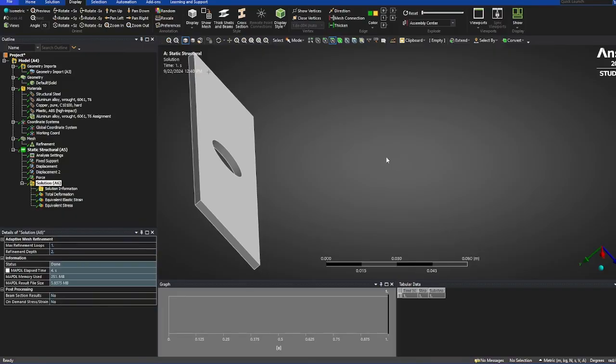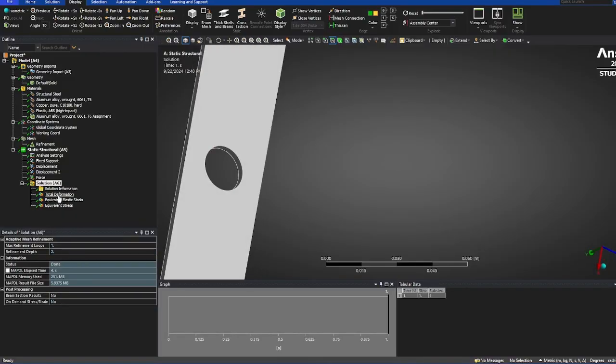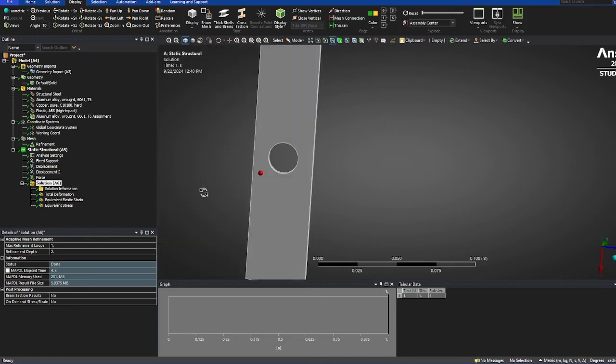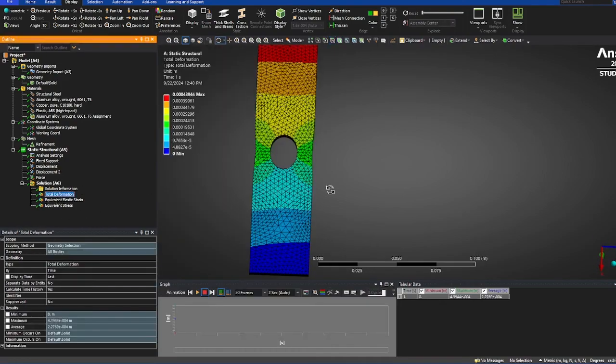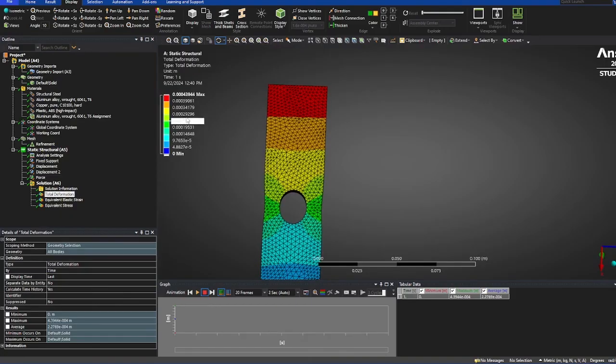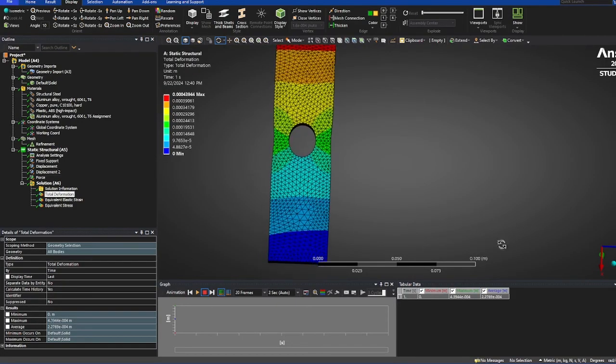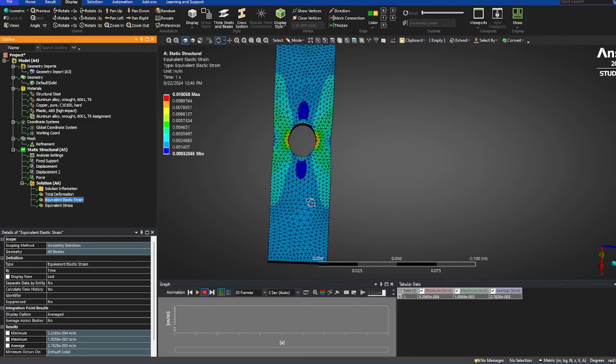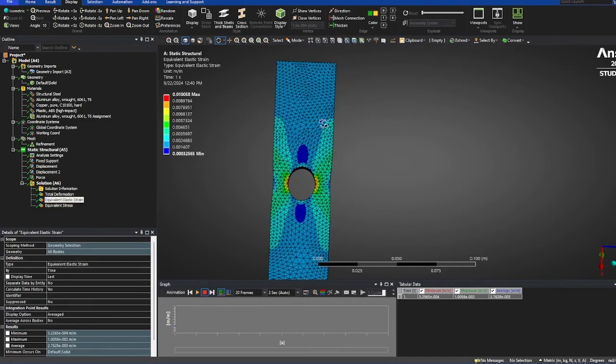So I'm going to rerun the study. And once it's done running, you can see over on the left, everything resolved properly. I've got my green check marks, so I can click on things and figure out where they went from there. In this case, my displacement study shows a pretty clear long displacement at the very end of the part. This is what we would expect. I should hope that the direction of pull is where we're going to see the most displacement.